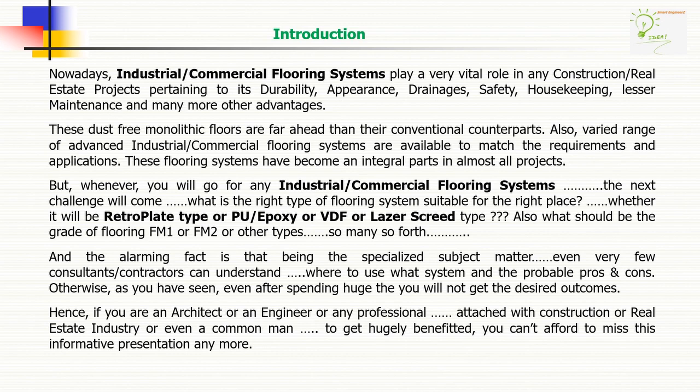But whenever you go for any industrial or commercial flooring systems, the next challenge will come. What is the right type of flooring system suitable for the right place? Whether it will be RetroPlate type or PU, Epoxy or VDF or Laser Screed type. Also, what should be the grade of flooring?